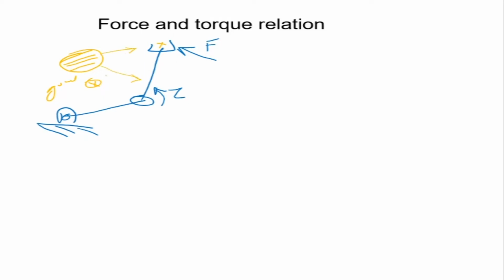So in each of these points, these are forces acting. These repulsive forces are forcing the manipulator away, whereas the attractive force is pulling the end effector towards the goal point. Again, it's a potential field method. So I'm going to assign forces, potentials, take the gradient, and then find the forces acting on these points. Maybe a point here, here, and here, and then find the effect of the forces on the torques, and then sum all the torques. Then go to my C space.